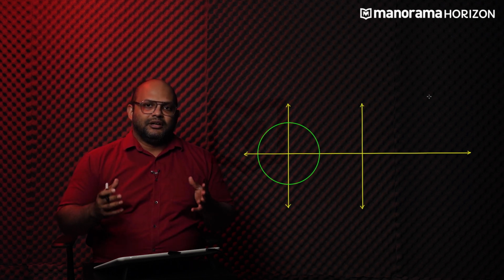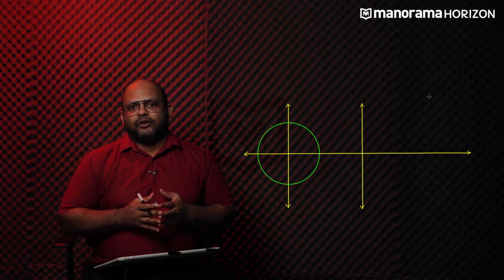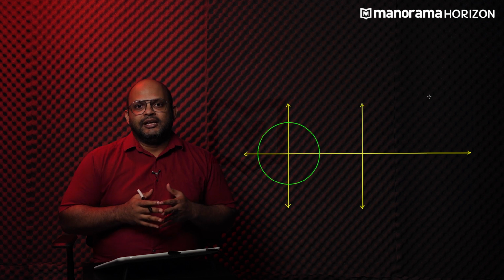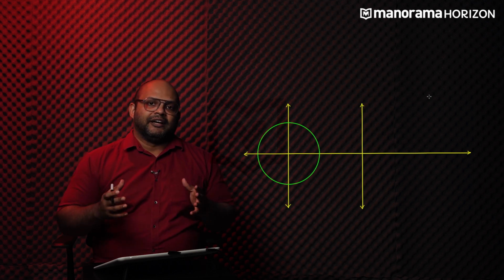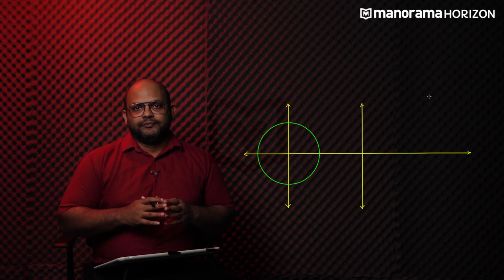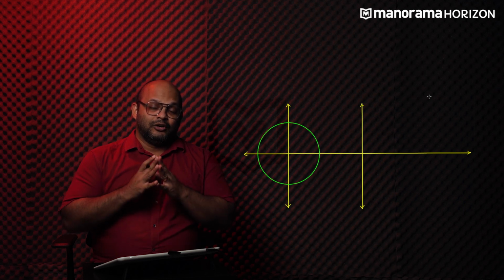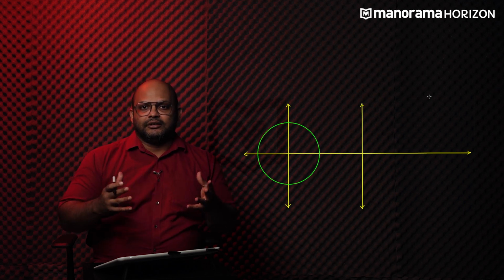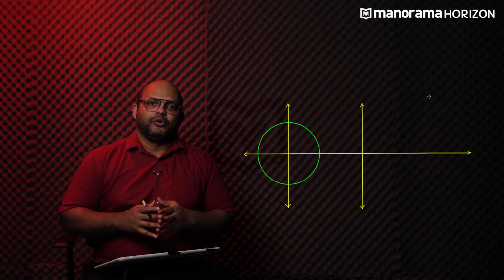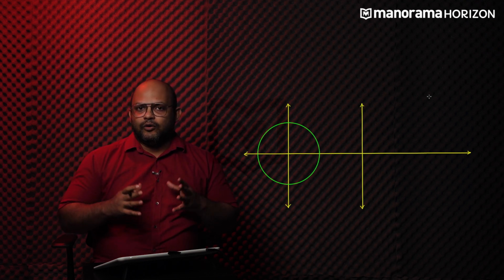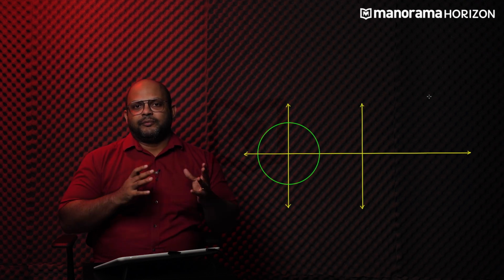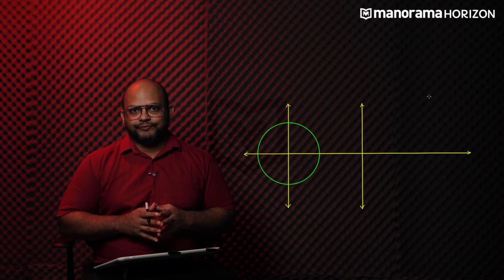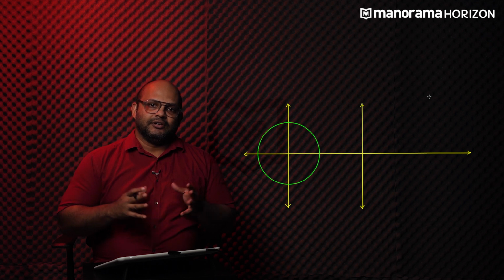So, we discover a unique and interesting property of these signals. We can describe a sinusoid, any sinusoid, as the rotation of a vector along a circular path. Please remember, voltage and current are not vector quantities. These are not vectors, but they can be represented using a rotating vector, which is called a phasor. Let us see how we do this and how we can use phasor representation to make visualizing these signals a little bit easier. So, here we have a circle.